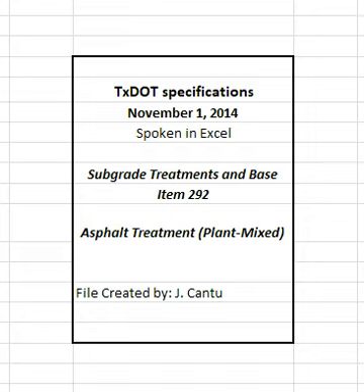4.6.2.2 Individual loads of asphalt stabilized base. The engineer retains the right to reject individual truckloads of asphalt stabilized base when it is evident that the material quality is unacceptable. When a load is rejected for reasons other than temperature, the contractor may request that the rejected load be tested. Make this request within 4 hours of rejection.